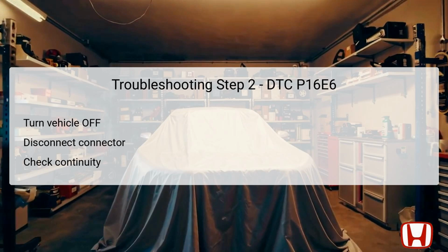To check for continuity, utilize a multimeter and assess continuity between specified test points. The test points consist of the female terminal number 7 of the transmission range switch, 10P connector, and body ground. Continuity indicates a complete circuit, whereas a lack of it could point to shortcomings within the wiring or bonding points, leading to the DTC being triggered.